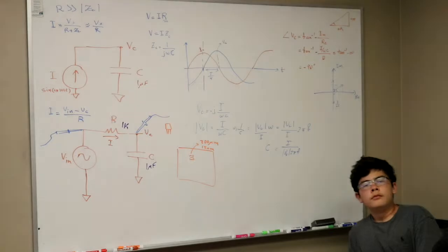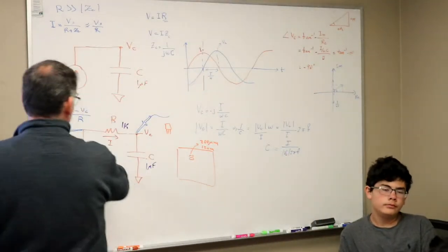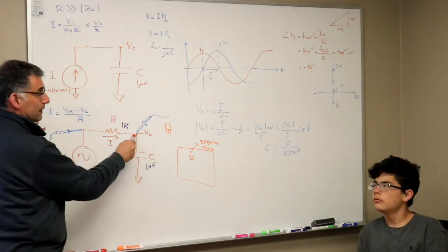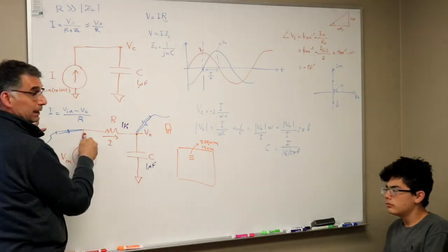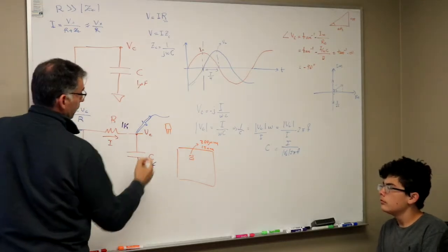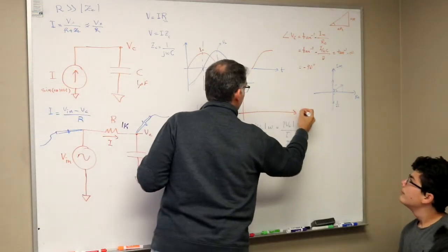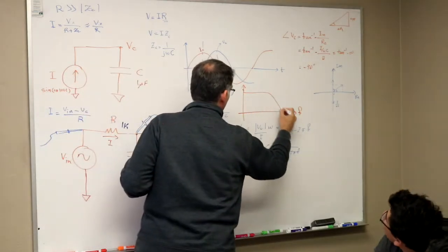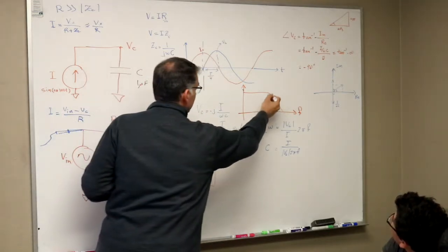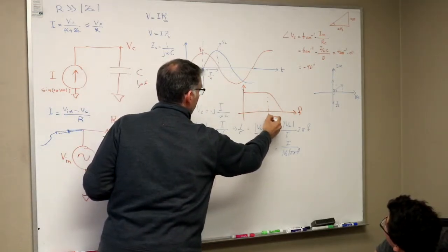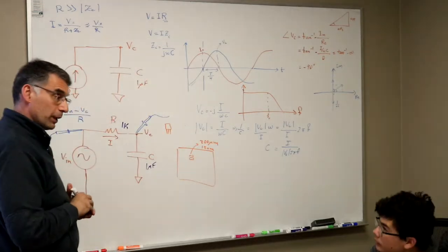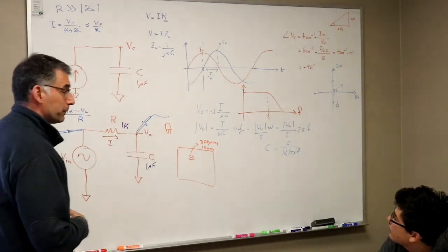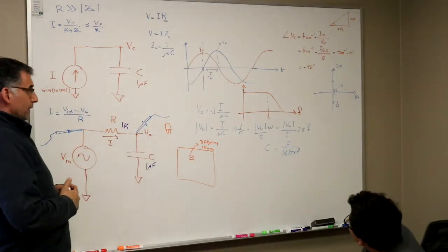As you guys observe, as the frequency goes higher and higher, the voltage across here drops. If you look at this voltage compared to this voltage over frequency, if I were to plot that, this would look like this. So there is a certain frequency which is called the corner frequency or the cutoff frequency, after which all the voltages are going to get cut off. It doesn't have enough time to charge up. So that becomes a filter.